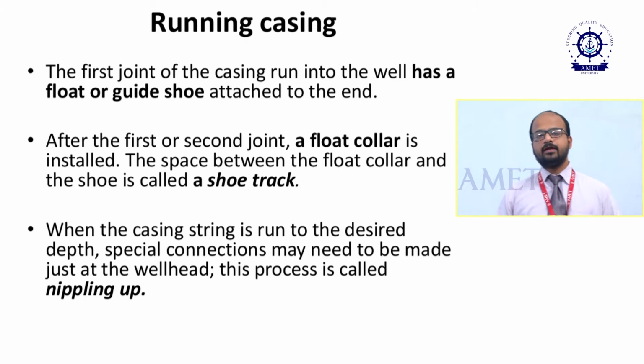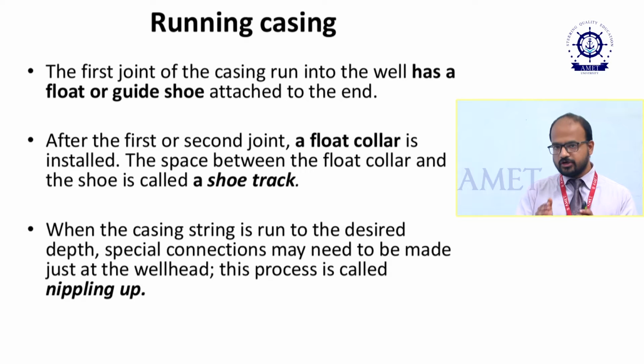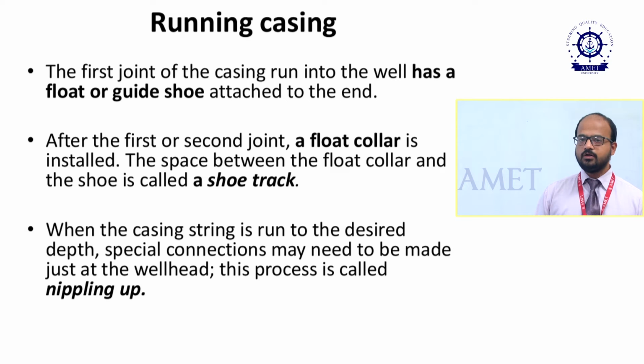So you cannot expect the hole to be even. Some of the hole may be enlarged, some of the hole may be caving during the entire time. So if it is like that, then what happens? If the end of the casing is plain, it may be damaged. So for that purpose, the last shape is thicker as well as spherical. That is your casing shoe, or your guide shoe. That's what we have to see here.